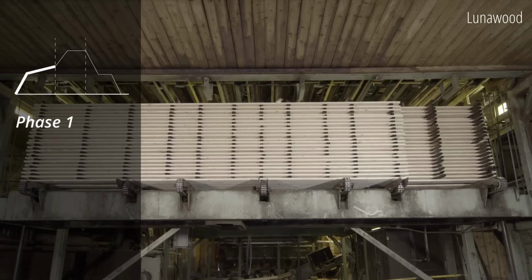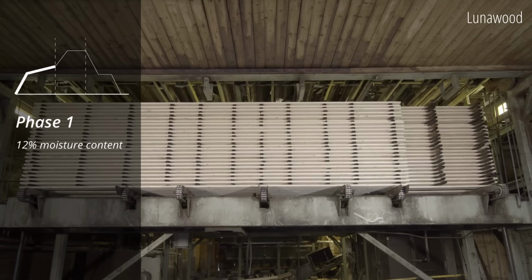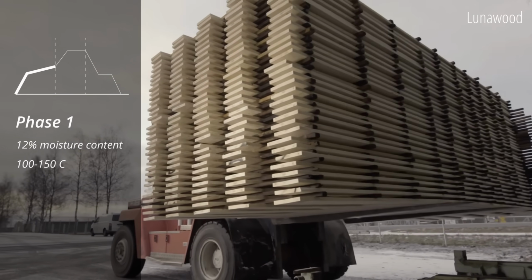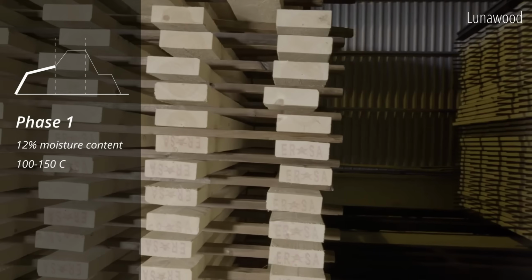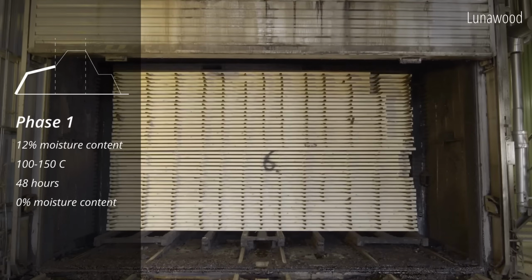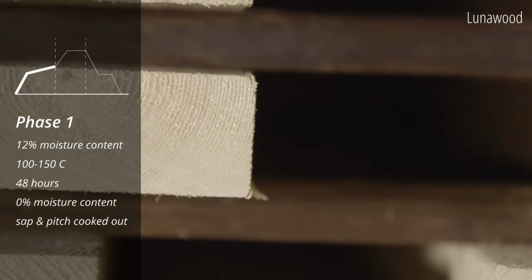In phase 1, carefully selected dried wood with a moisture content of 12% is placed in a kiln. It is heated to 100 to 150 degrees Celsius for 48 hours. The moisture content of the wood is reduced to nearly zero. The sap and pitch are also cooked out.